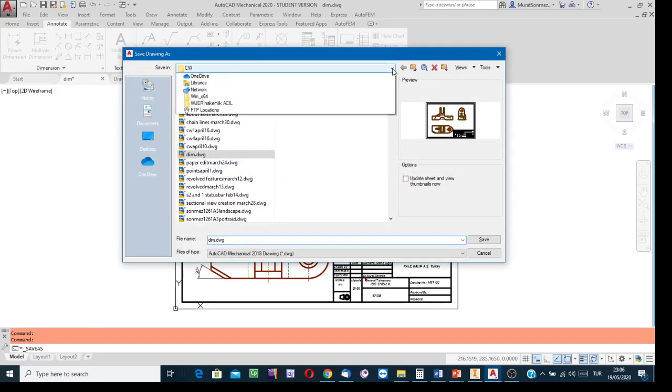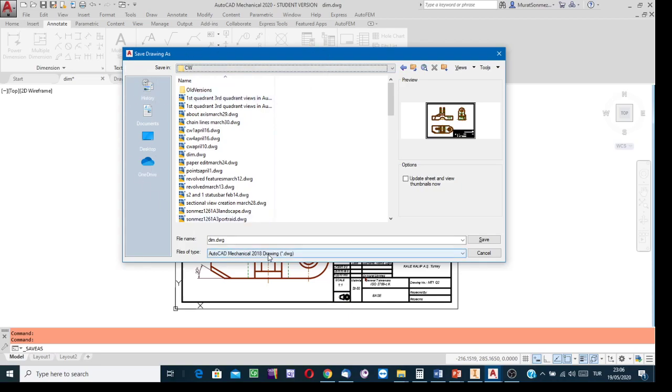Okay, show the address. Although you selected the save as option, if you couldn't find the save dialog box, this means you need to press the escape button first and then write this command, FILEDIA, to fix the trouble.